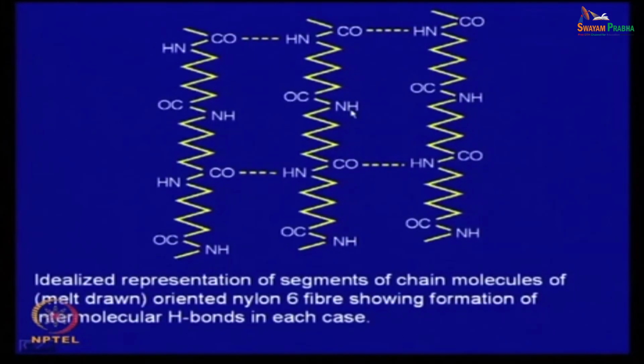The melting temperature is not all. This hydrogen bonding makes them crystalline, makes these polymers stiff, makes these polymers strong. Now, this nylon is so strong, provided the length between two polar functional groups, the amide groups, is regulated. Then one can get a very tough and strong polymer, which is used for making mechanical gears. Mechanical gears are made of this nylon, self lubricating gears. Self lubricating gears are made from these polyamides.